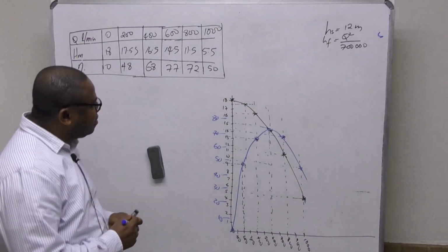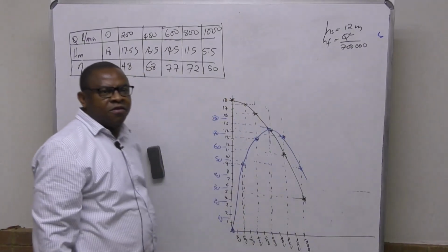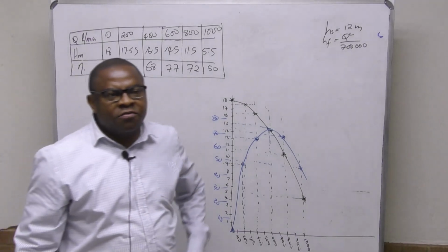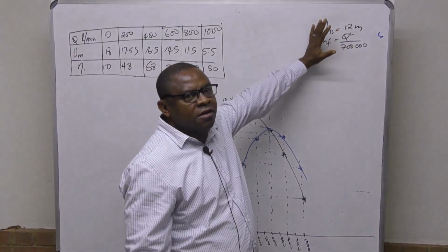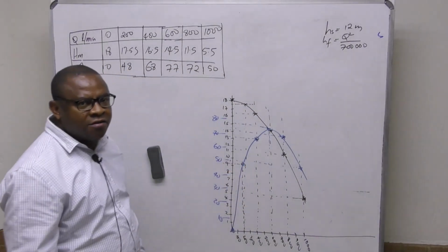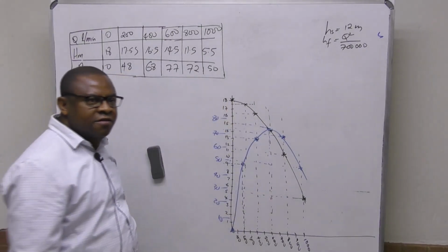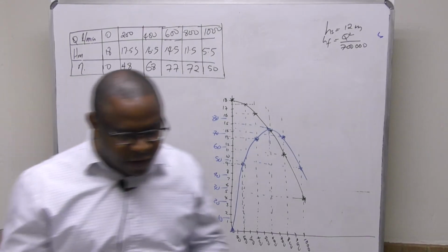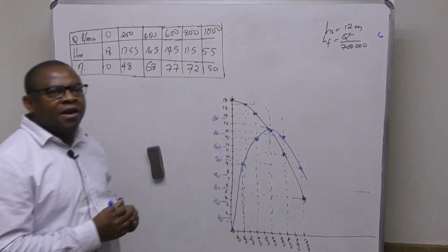All right. So now, this is the pump's characteristics, which includes the efficiency. Now we're going to mount this pump and subject it to this head. I will be able to sketch the system characteristics and see where the pump characteristics will meet the system characteristics. From there, we'll be able to get the operating point. Okay? So now, let's start.